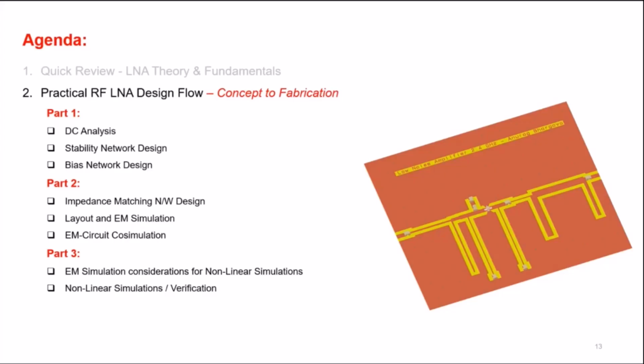When I buy a component from Mouser, I only have the part number. Yep. So once you have the part number, you should go to the manufacturer's website, and from there you can get an S2P file. Sometimes even DigiKey has S parameter files available for you to download. Otherwise, DigiKey is just a supplier. If you are buying, let's say, a Skyworks or a Qorvo or MACOM device, you will always have the part number. Go to those manufacturers' websites and they will have an S2P file, or contact their local distributor.